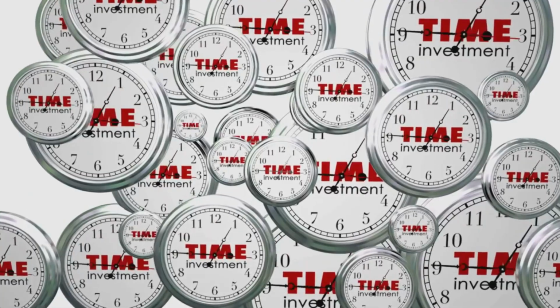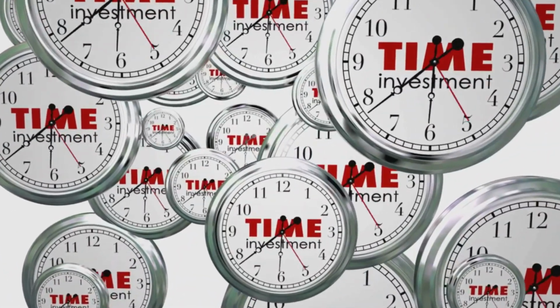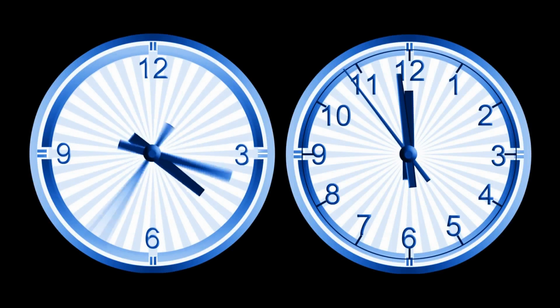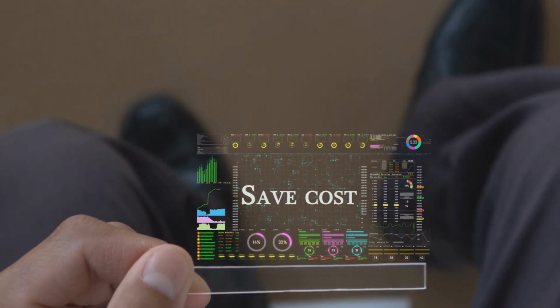On the bottom, we total value added time, the time spent actually transforming the raw materials into a finished crayon. We calculate that it takes just 155 seconds of value-added time to create a crayon. But the total lead time, 8 hours. The difference between value-added time and lead time is staggering. Only a tiny fraction is real value, highlighting the vast amount of waste in the process.